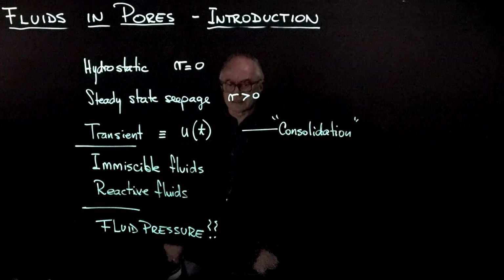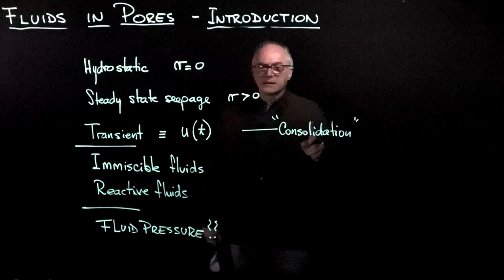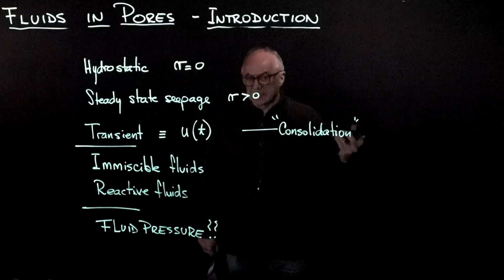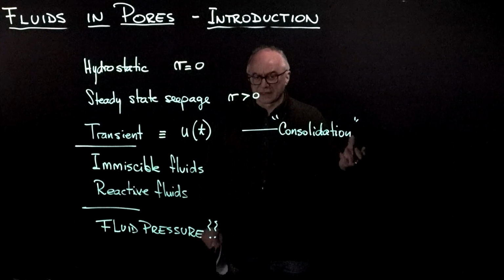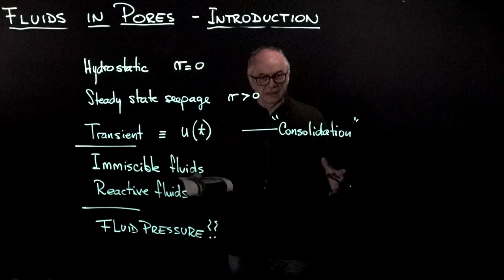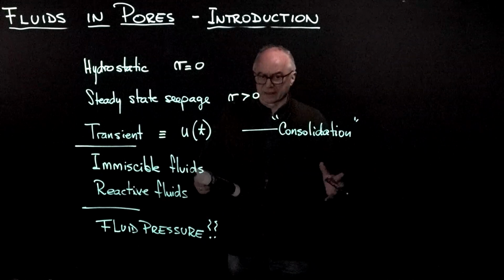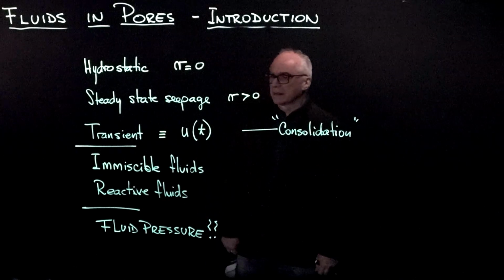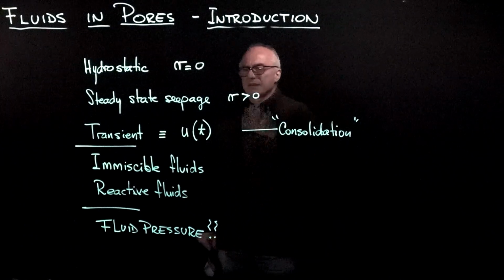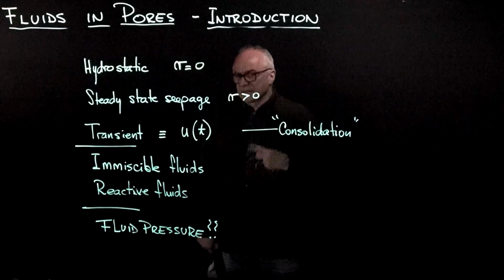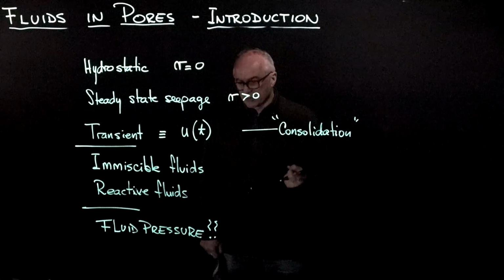In the geotechnical engineering community, please be careful, because consolidation has a different meaning in other fields. Like for example, a consolidated material for petroleum engineering is a cemented material, a cemented sand. So these are our three basic situations with fluids in pores, but the story gets rapidly more complex.